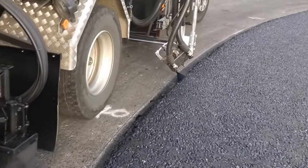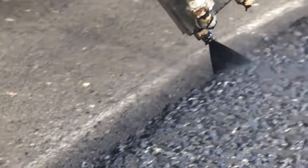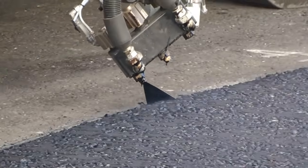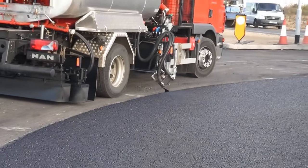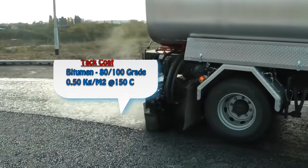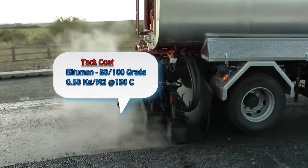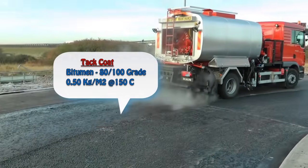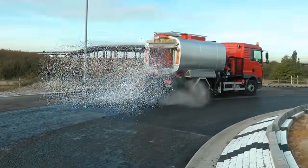The tack coat is the binding layer between two bituminous surfaces. The bitumen grade 80 to 100 is used for the tack coat, and it is heated to around 150 to 160 degrees temperature and uniformly sprayed at around 0.5 kg per square meter with the help of a mechanical sprayer. Normally, it is sprayed just before laying of the next layer of asphalt item.